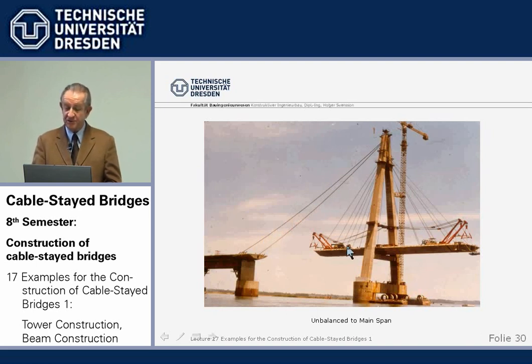Okay, you can do it this way. You either are here balanced, then this has a minimum strength, or you go one ahead only in the main span to stress this cable. And in that way you can get rid of the long forestay auxiliary cable endangered by ship impact.